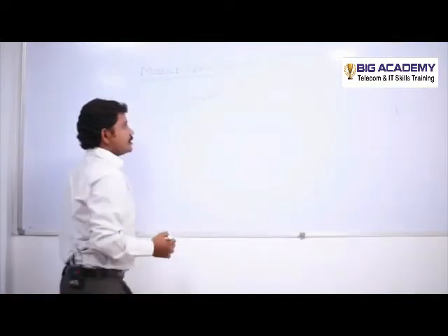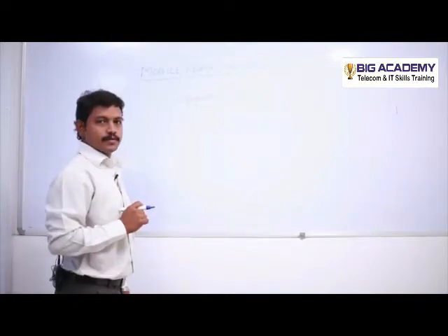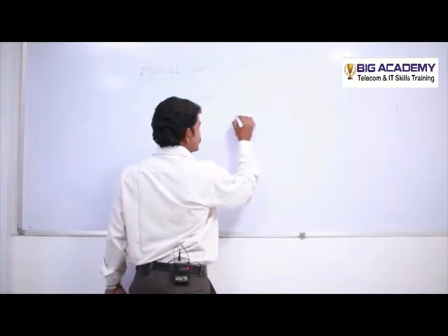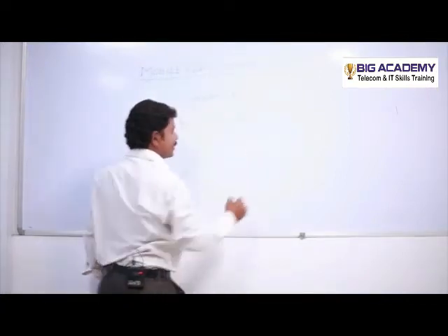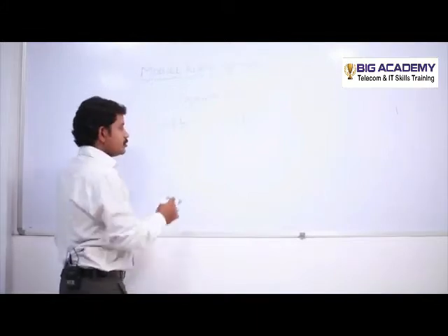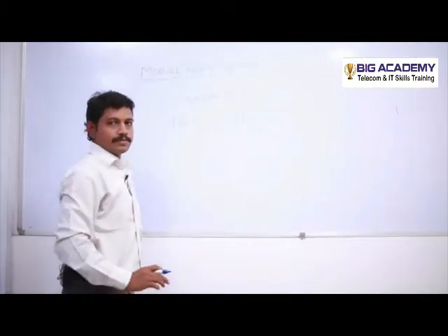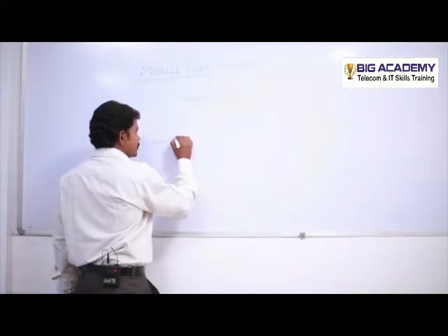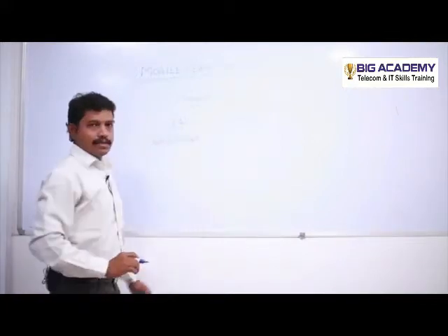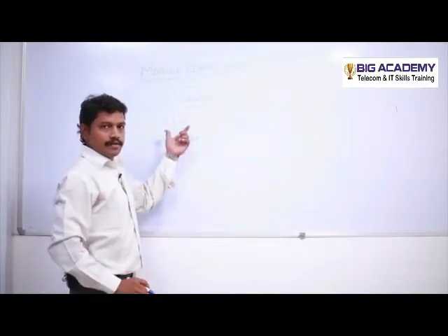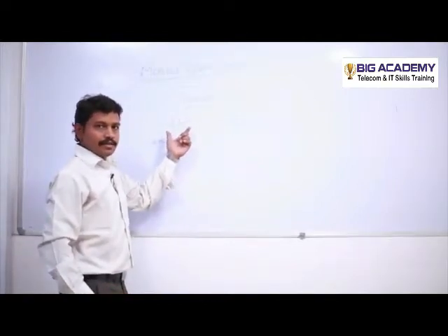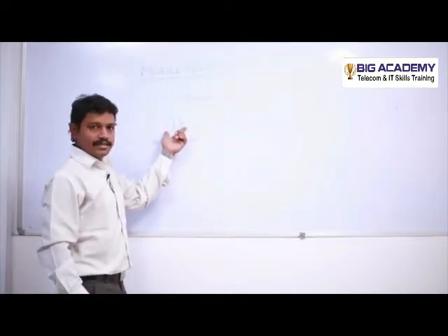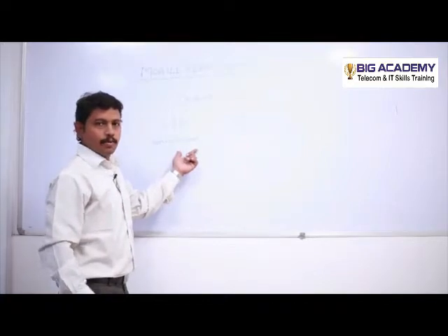Capacitor can be mentioned as C in circuits. The symbol of the capacitor is parallel plates, and another one is one straight line and one curved line. So it's of two different types, and this is non-polarized, which has no polarity. Polarized means wherever we have plus and minus signs. If there are no plus and minus signs, we call that non-polarized.